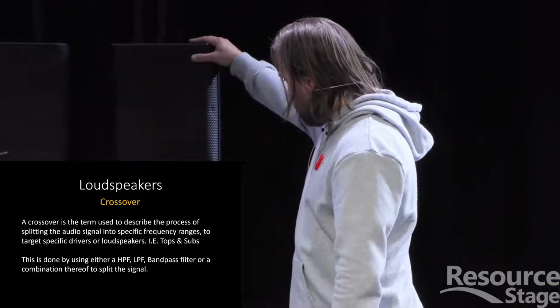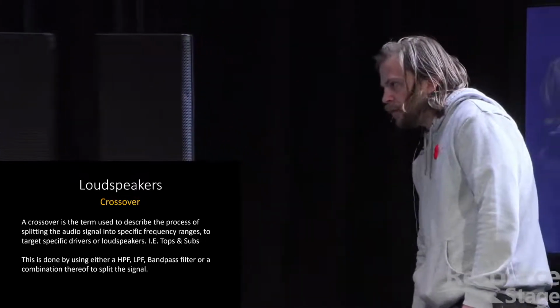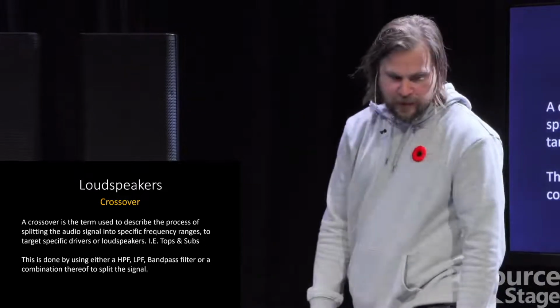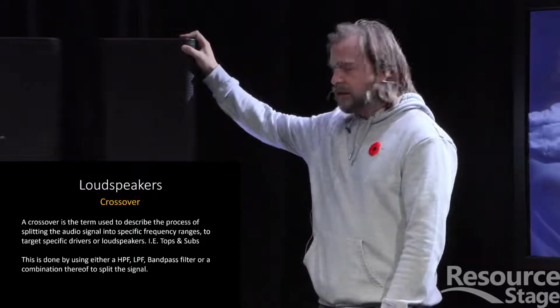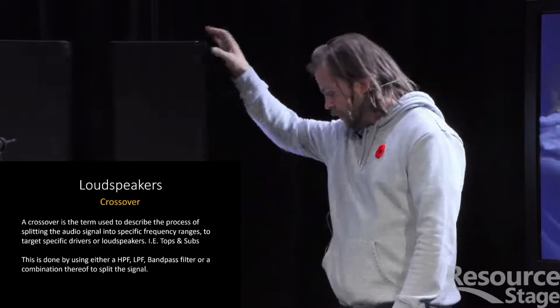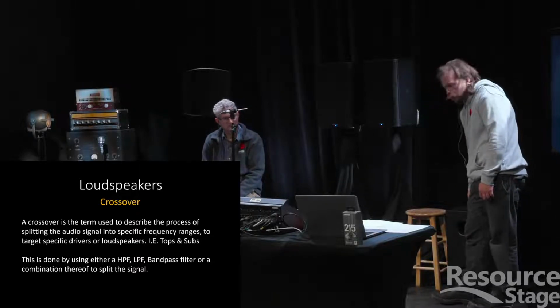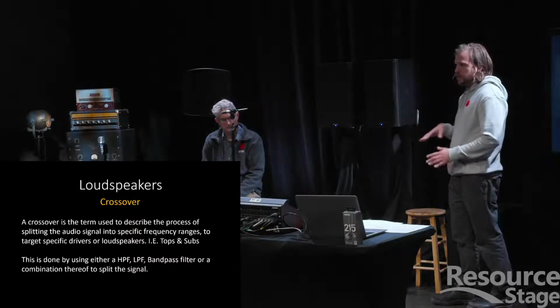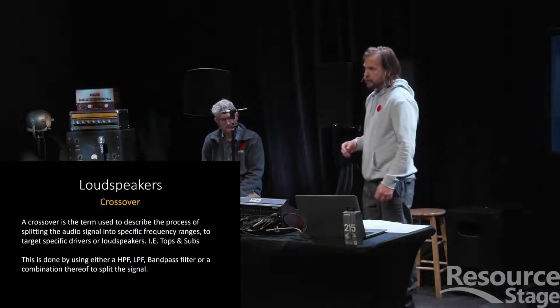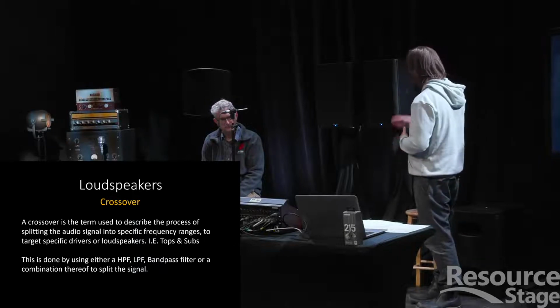Here we have a QSC K2 series and a QSC KS112 K-sub. The frequency range of this speaker is approximately 56 hertz to 20K. And the frequency range of the subwoofer is 41 to 108 hertz. So there's overlap between these two speakers without any crossover involved. The idea with the crossover is using high-pass filters and low-pass filters, we can carve the sound so they're not overlapping.